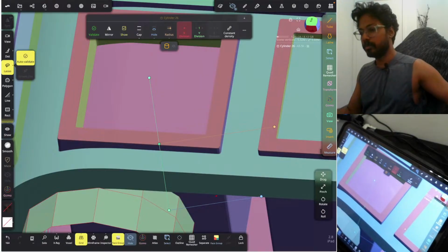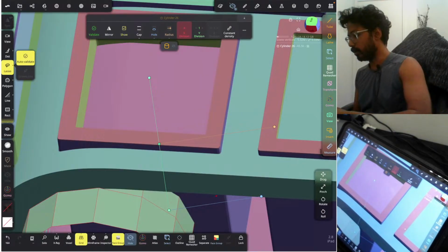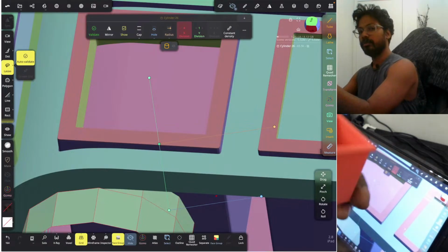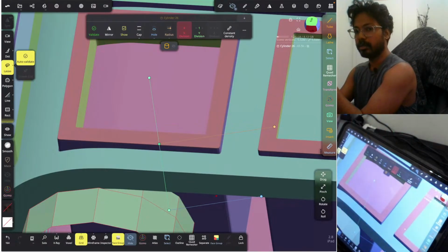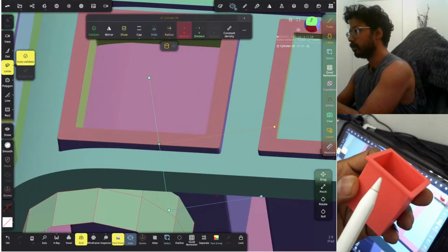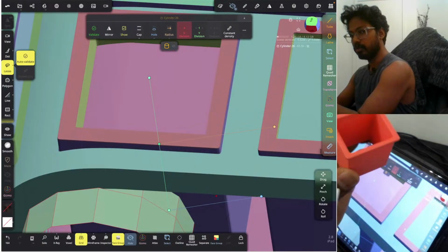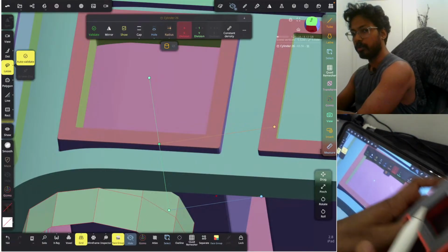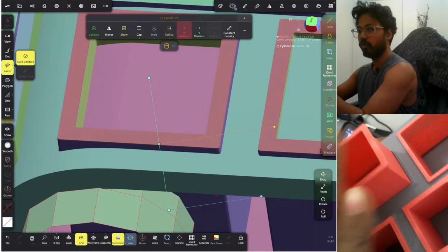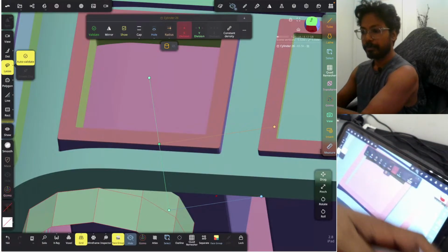So per side 0.1 mm I gave the clearance. If you see the top edge is a separate cylinder and the bottom is a separate cylinder, both combined together, that is one body with 0.1 clearance on all the sides, and it just goes in.